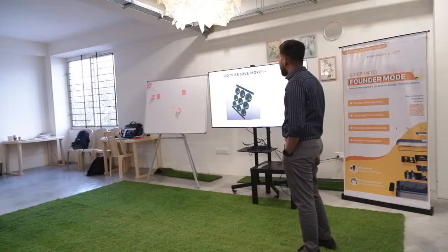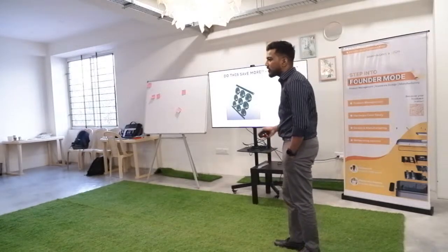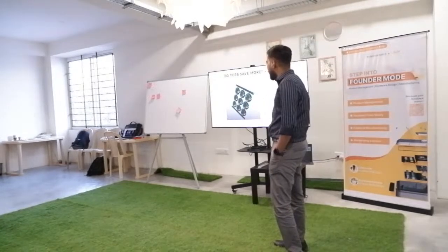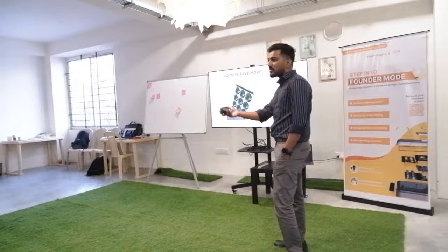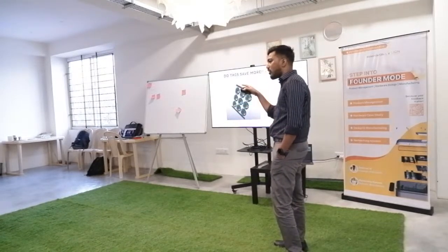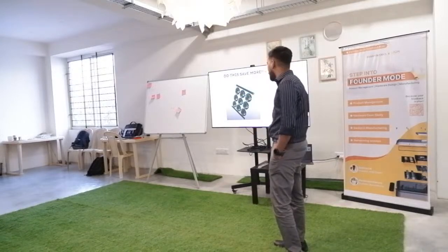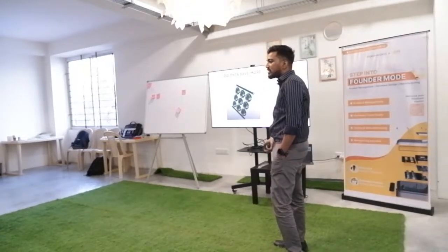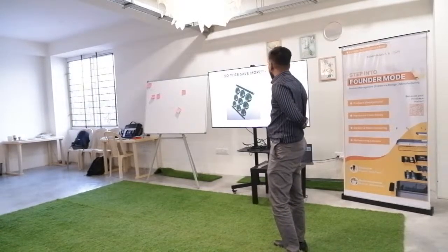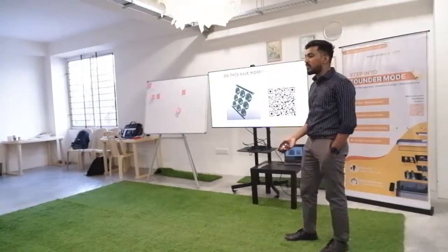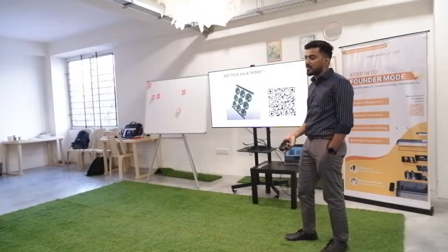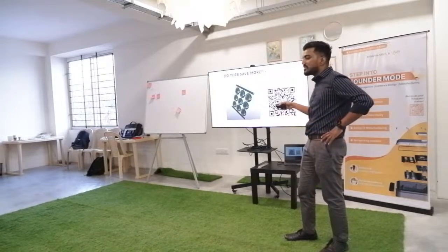The other way is to panelize. Sometimes you might put your design in any platform and check the price, so it's always a good option to do panelization and check. Obviously LionCircuits has their own inbuilt panelizer called LC Panel. You can just drop in your Gerber and increase how many rows and panels you want. Since it's getting panelized, the cost of a single PCB will be cheaper than getting individual PCBs. This video is explaining other features, so I am not talking about panelization in depth. There are features like V-grooves, mouse bites, and how we can combine different PCBs. All those things are in the video.